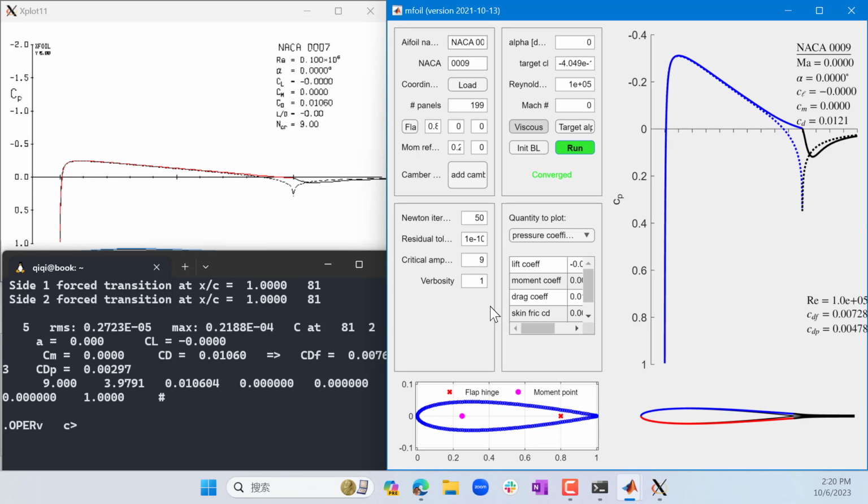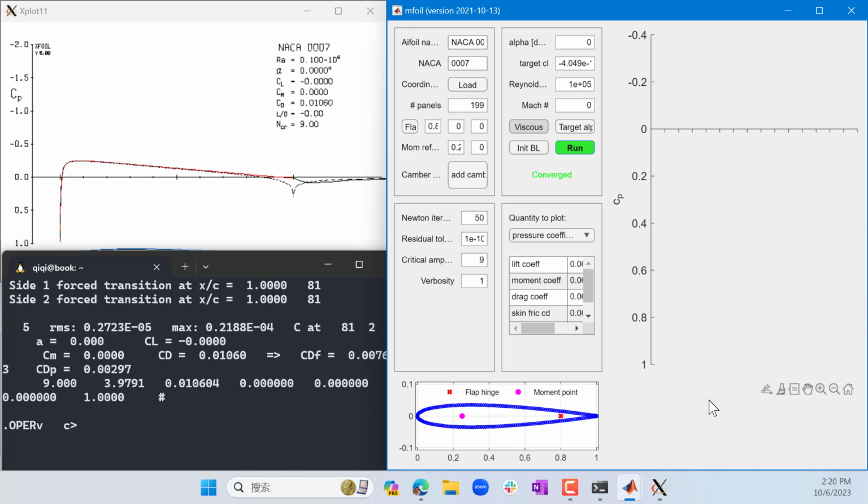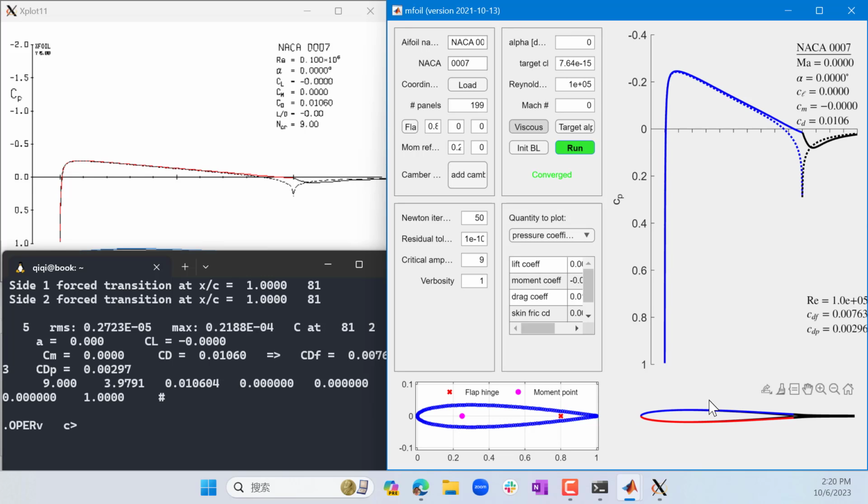So by mass conservation, the same mass has to go through a smaller area, meaning the flow velocity has to be higher and the pressure has to be lower. So basically, a thicker airfoil means lower pressure. The boundary layer makes the airfoil as if it is even thicker, and as a result, makes the pressure even lower. Okay, make sense? All right.